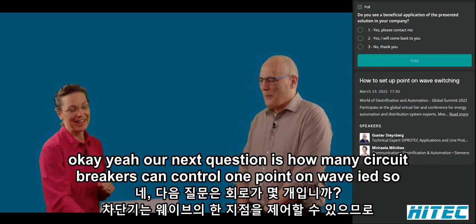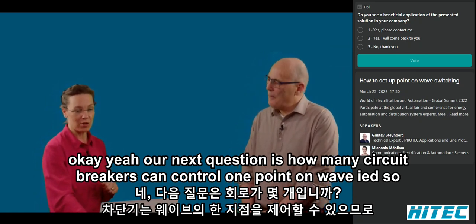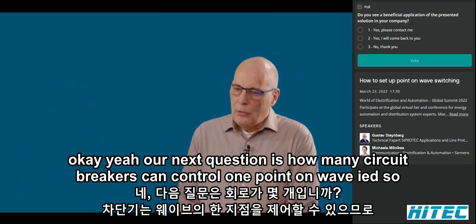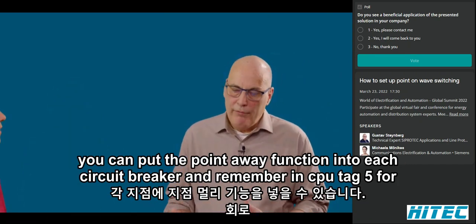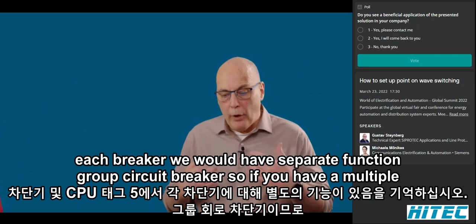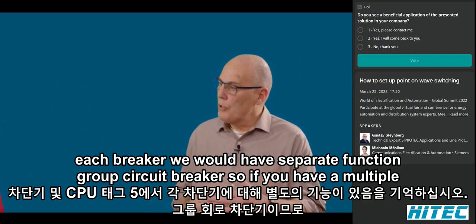Okay, yeah. Next question is, how many circuit breakers can control one point-on-wave IED? So you can put the point-on-wave function into each circuit breaker, and remember in SIPROTEC5, for each breaker we would have a separate function group circuit breaker.